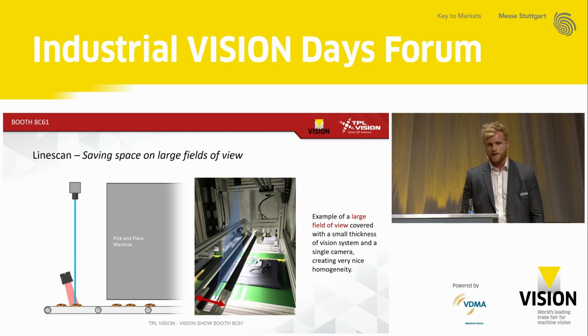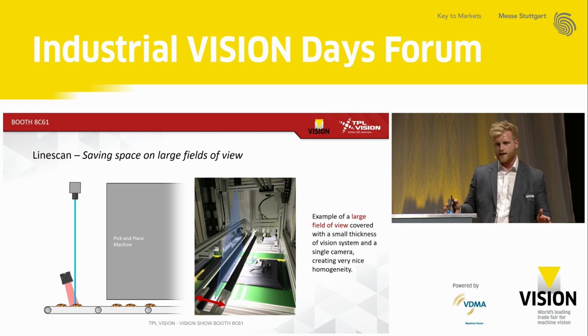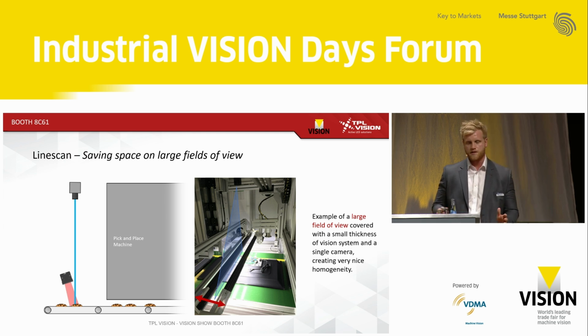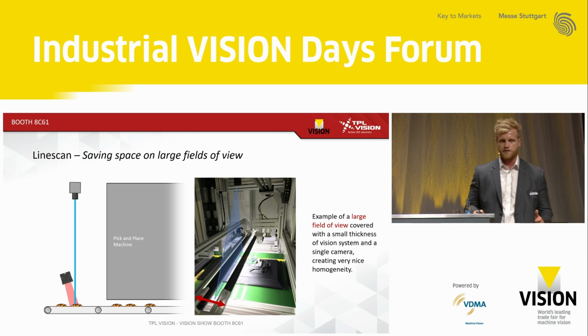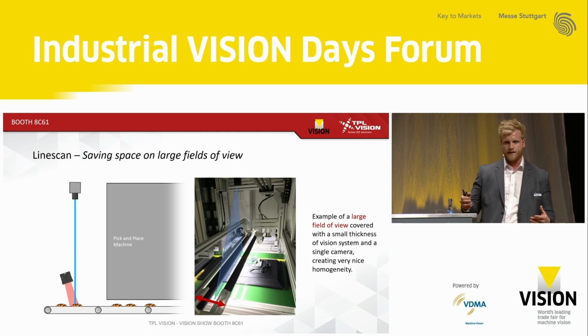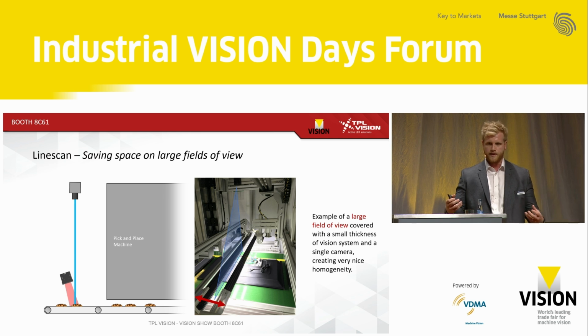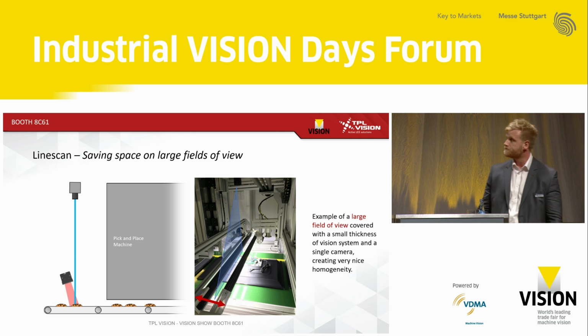The most important thing of line scan is that the light is really uniform. You want to make sure that the light is uniform and really intense. But the good thing with line scan is actually much easier to get these parameters because you can mount the light very close to the field of view. This means you can take advantage of it being a real uniform light. You don't get the effects of parallax as badly as what I was talking about in the early slides, where the reflected light can change a lot depending on where it is on the field of view.